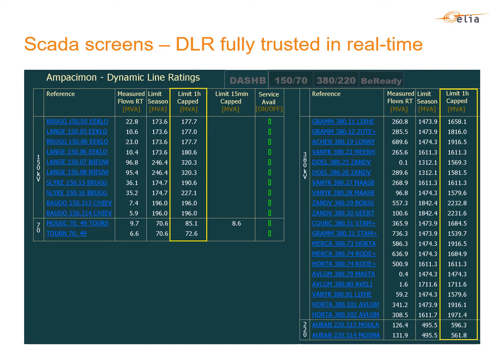The actual line rating changes in real time according to weather conditions, which is not stable throughout an hour. And this is why, for the application here in Belgium, the customer requested to display in the SCADA the 1 hour ahead forecast rating, which is the minimum value of the dynamic line rating based on weather forecast over the next hour.